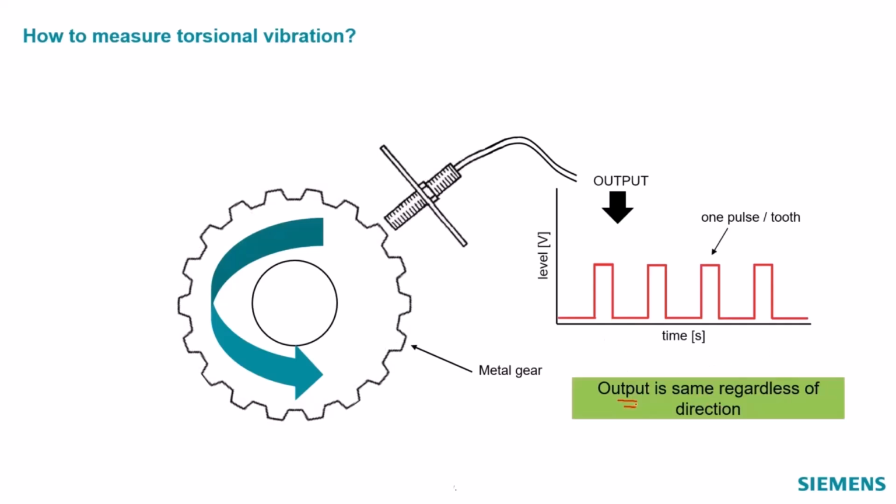Would it be a problem if your rotating system started rotating backwards? Yeah, I think we would want to know that. Some systems are not designed to rotate backwards, like a combustion engine. So if it was rotating backwards, you have a big problem. If you have something like an electric motor, those are actually designed so they can rotate equally well forward or backward. But again, you wouldn't know with an encoder like we're talking about here whether it's going forward or backward. There are devices that allow you to tell the difference.